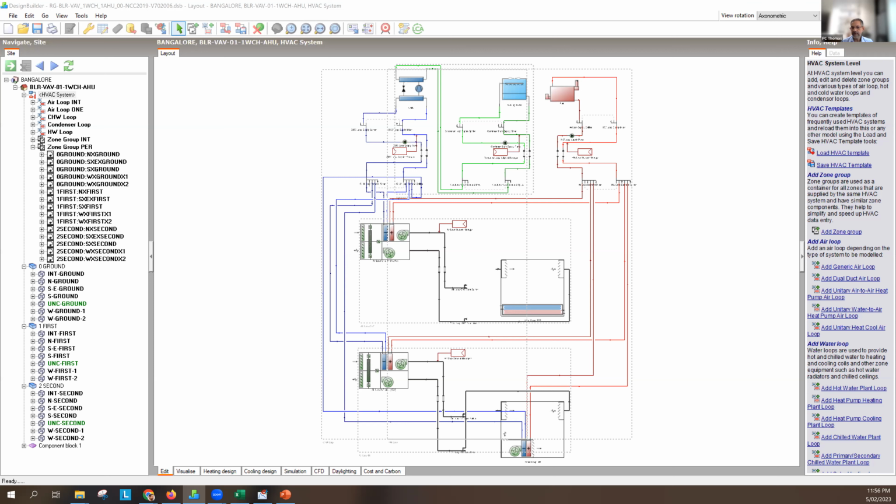Well, the typical refrigerant being used in VRF systems or split systems, and you can go and have a look at that, they use high pressure refrigerants, R410A, those kinds of refrigerants. They've got what we call very high global warming potential. So if you lose 1 kilo of this high pressure refrigerant, it is equal to, in some cases, 1900 kilograms of CO2 greenhouse gas emissions.